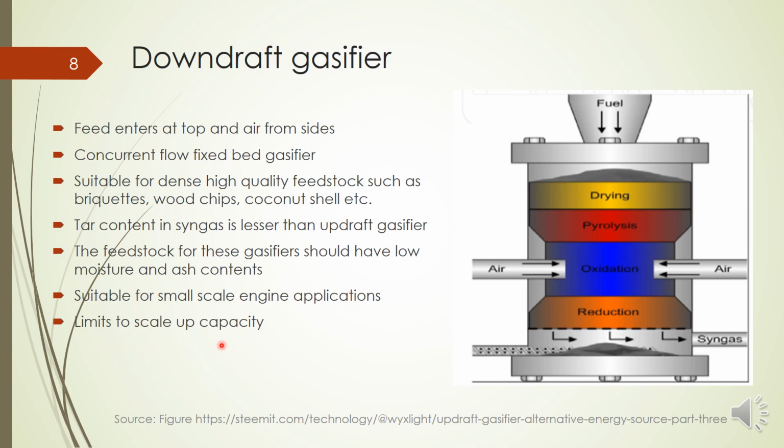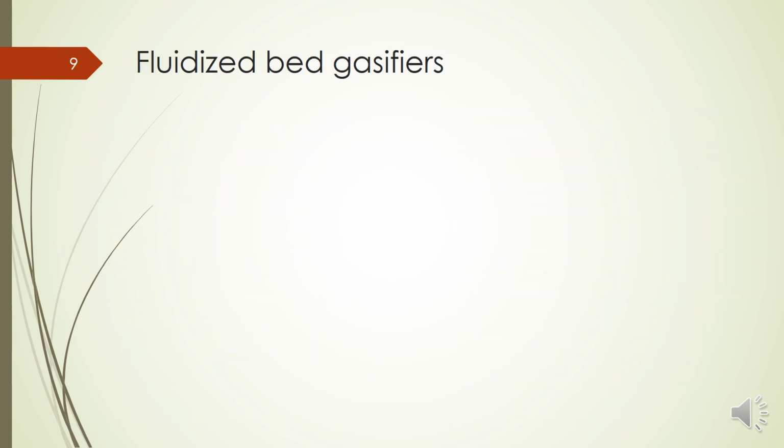But the problem is these fixed bed gasifiers, that is both updraft and downdraft, are not suitable for scale up capacity. So if you want a very large capacity gasifier, these fixed bed gasifiers are not that applicable. And here also we have a chance of clinkering, bridging, etc. The problems with ash agglomeration, fusion of ash, etc. will happen here also.